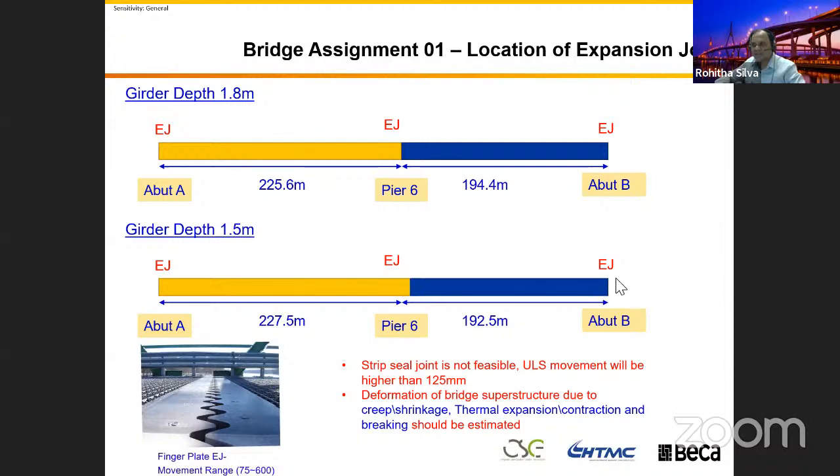Here it is opening up, this is closing. The creep and shrinkage at the abutment location is opening. That means shortening the length, opening here, right? The shortening in the length here, the opening as well. It works the same way, but it's doubling up. So you need to calculate this joint length in a proper way, and then calculate what is the required gap.